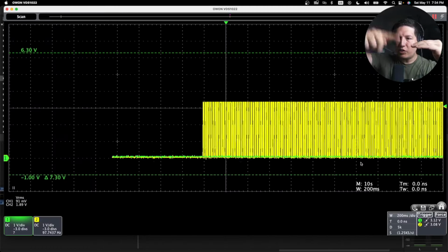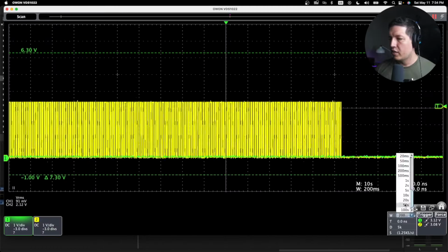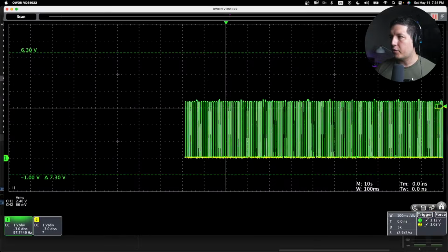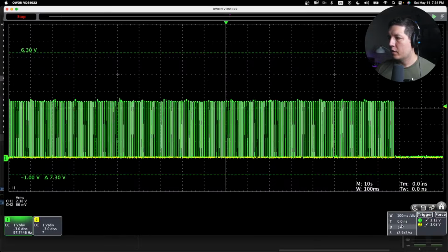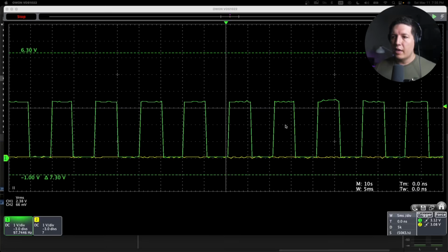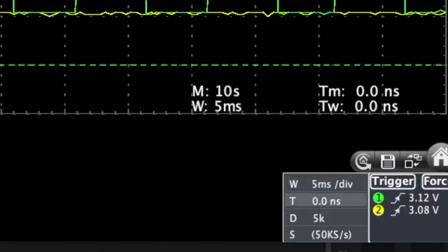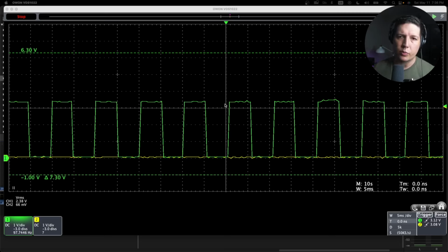Okay, so what you see there is all the PWM pulses going back and forth. And if I freeze this and then expand it, we see that this system is pretty accurate. Granted, we are operating at a very slow frequency. But roughly, it seems like the GPIO stays on the high voltage for 1 square, which corresponds to 5 milliseconds, and it stays off roughly for 5 milliseconds as well. Roughly, this is not super pretty, but it will do the job for controlling a DC motor.